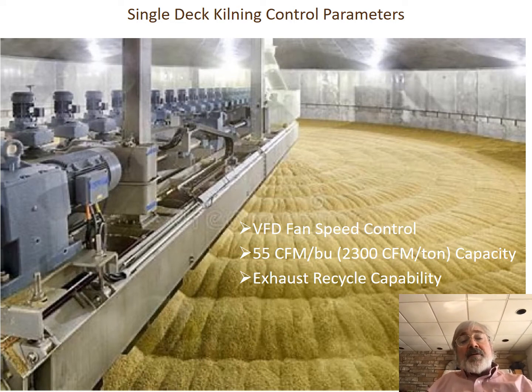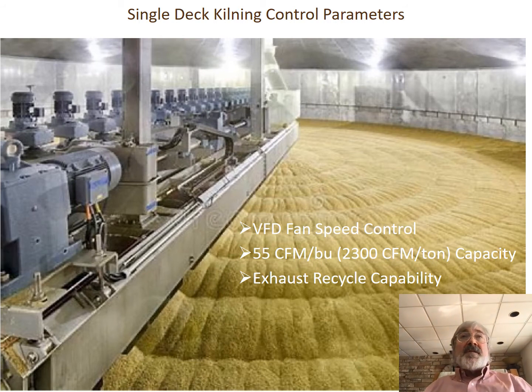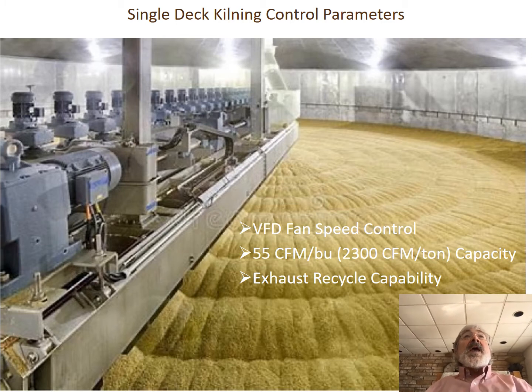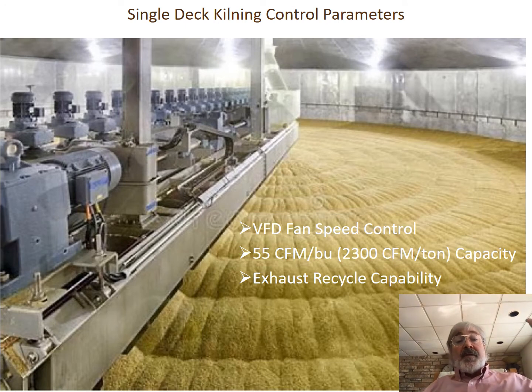That comes right out of Anheuser-Busch, and I like that as a capacity minimum because with that capacity, you can achieve less than a 24-hour cycle. What that means is if you're running full tilt and producing a 24-hour kiln every day, 55 CFM per bushel will get your kiln dry and allow you time for emptying and refilling within 24 hours.